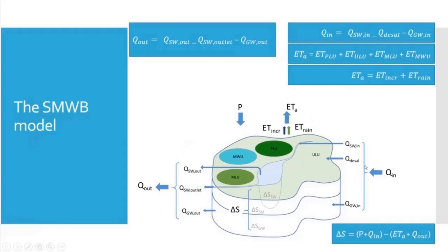And in water accounting, if you remember in the OCW course, we have 4 types of land use categories in water accounting plus, and also the change in storage. So the evapotranspiration, the actual evapotranspiration, is the sum of the evapotranspiration from the 4 types of the land use cover, which also should be equal to the sum of the blue and the green component of the evapotranspiration.